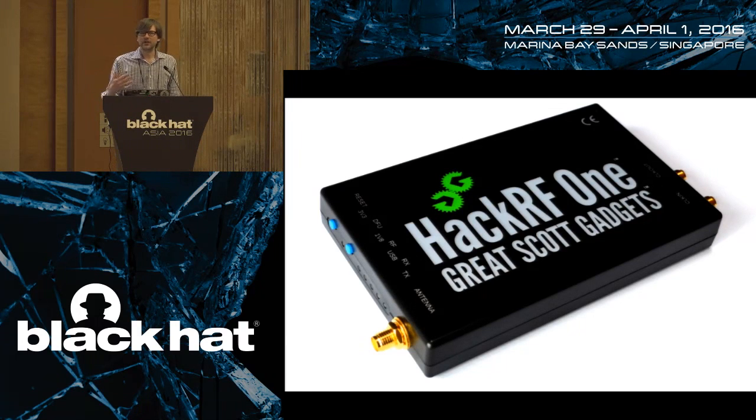And so as a receiver, what it does is you connect an antenna to it, and it samples or digitizes the radio waveform that it's receiving, and then gives me over a USB connection to my host computer a digital signal that is representative of the analog waveform, kind of like a sound card, but about 1,000 times faster, so that it can sample radio waveforms instead of sound waveforms.